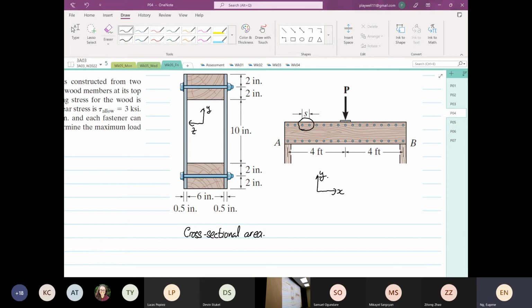And the textbook got it wrong. I'll tell you what the textbook got wrong. The textbook got it wrong because they do this first and then do thin wall analysis. Wrong. You have to teach thin wall analysis first, then you can do failure like this. Okay? So now, where it will fail, okay, there are two regions where it will fail. It will fail due to the shear at the centroid, okay, thin wall. It will also fail at the joints, okay.